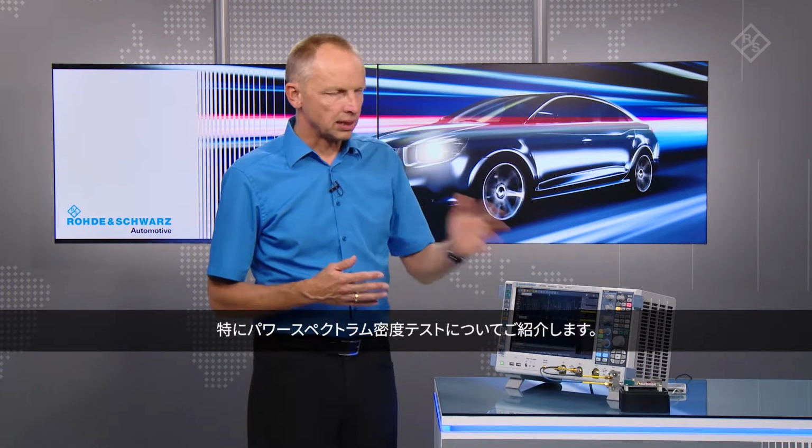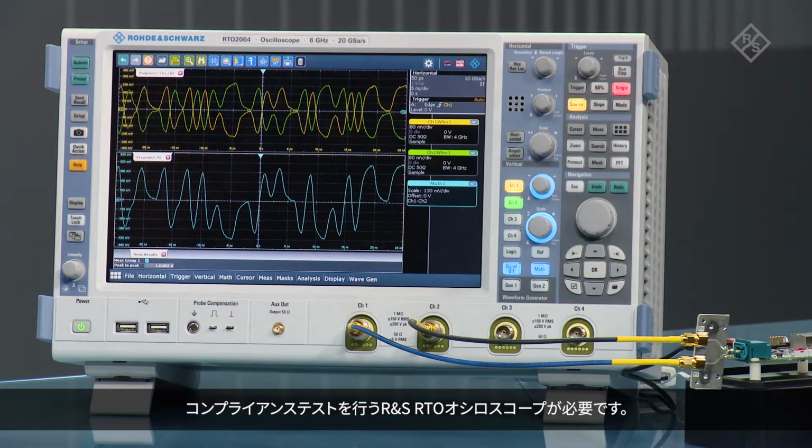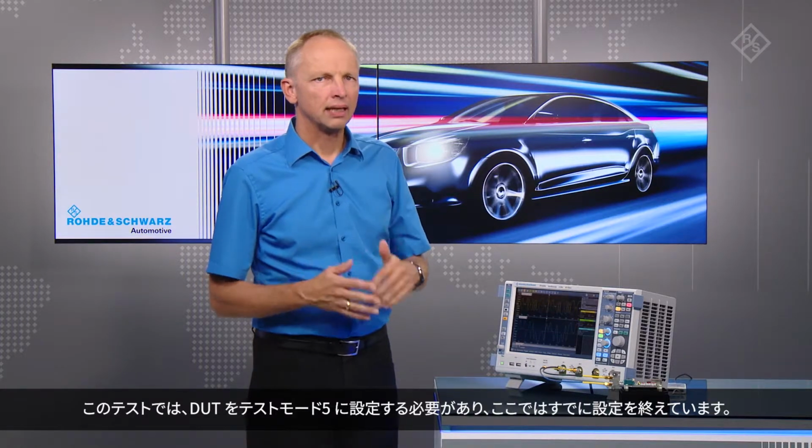Hello, in this video I want to show you 1000Base-T1 compliance testing, and especially the power spectral density tests. For this you need a DUT that's capable of 1000Base-T1, that you see here, as well as an RTO oscilloscope that does the compliance testing. The DUT needs to be set up in test mode 5 to do that.